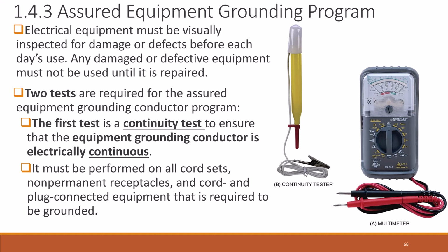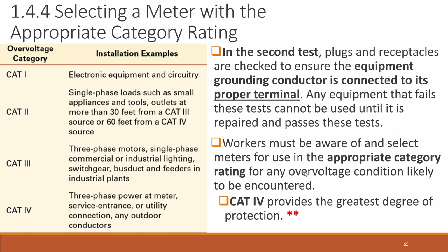And these are typically the tools you might use. So the continuity tester you can use, but you can use most multimeters as continuity testers. And so typically a meter is used for both, I think, in the real world. But this little continuity tester could test for continuity to make sure there's no shorts, there's no loose wires and that sort of thing.